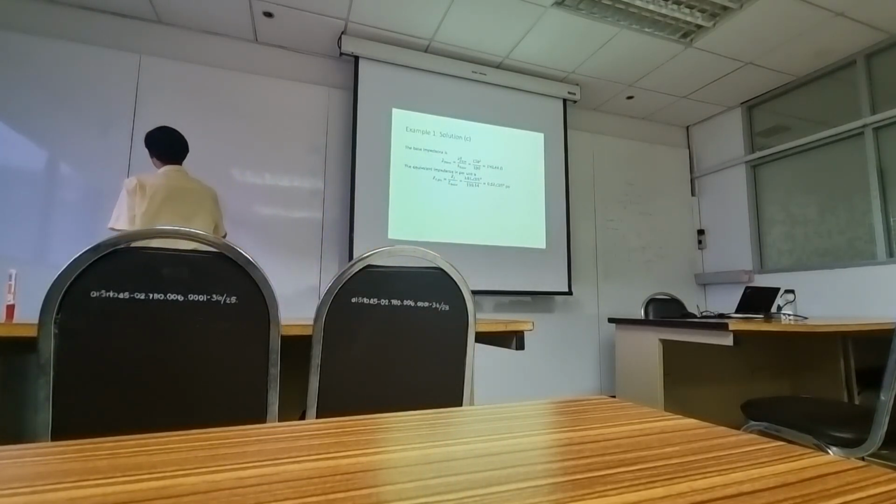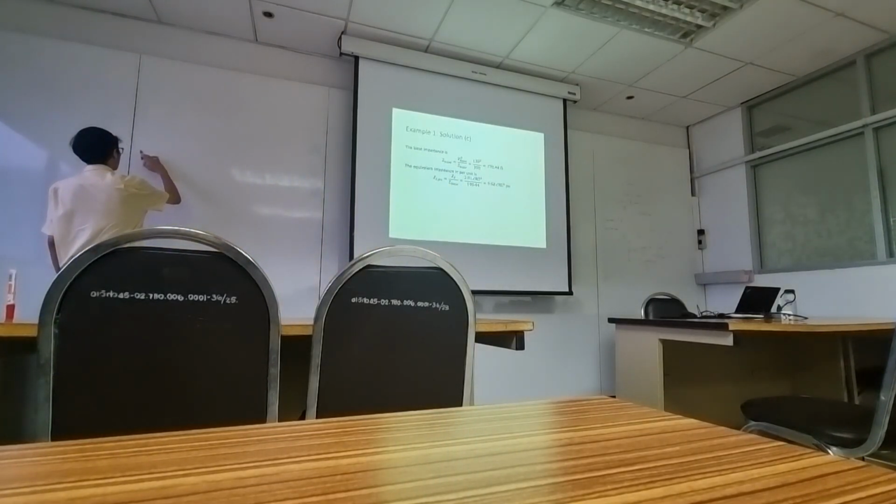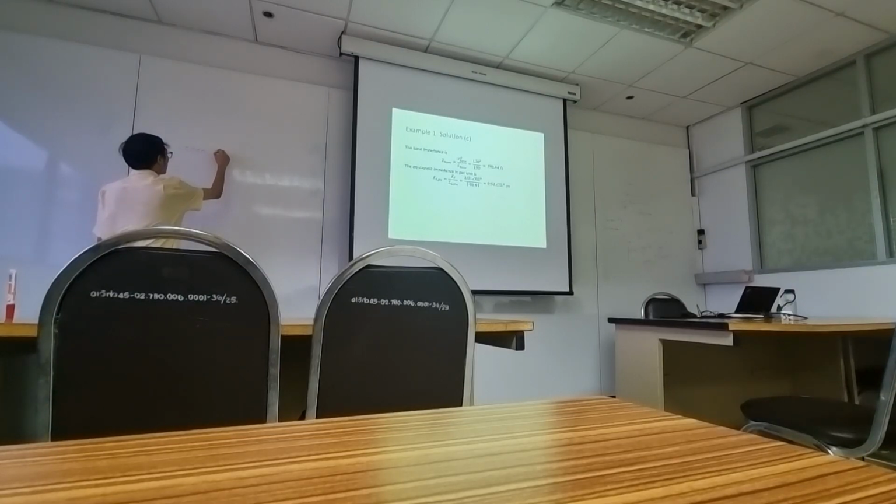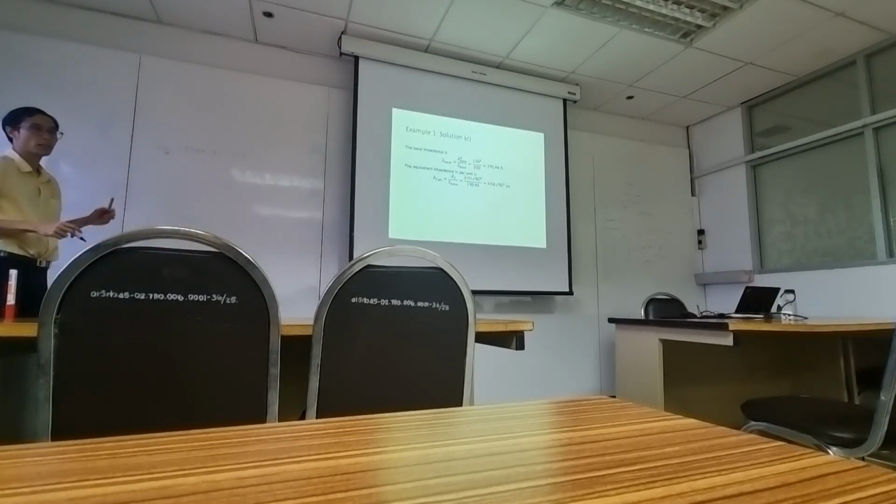If you try to calculate the short circuit capacity, this is 3 phase, and this is 5,000 MVA, angle 85. Okay, this is in real unit.